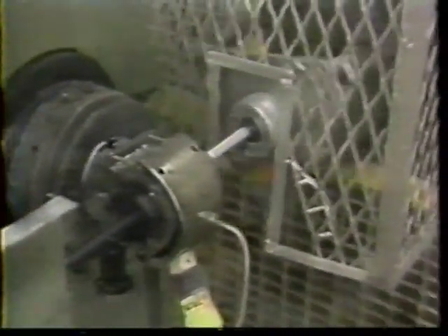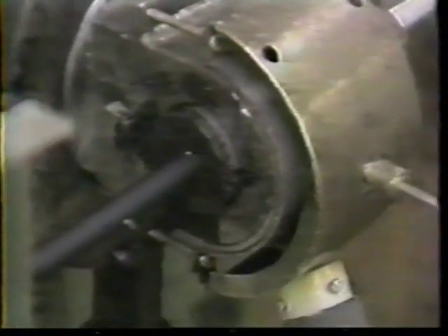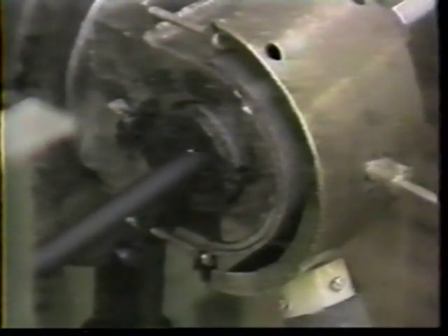To enhance the strength of the cable, a bedding layer is applied and a second set of strength members is added. Notice that the second set of strength members is applied in an opposite lay from the first set. This technique minimizes any twisting forces in the finished cable. Finally, another pressure extruded jacket is added, and its diameter and length are measured.